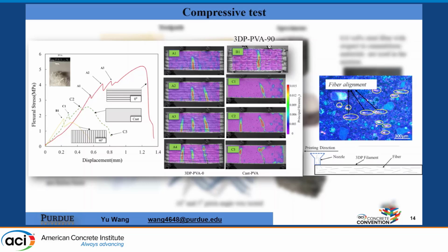This will strengthen the filament without influencing the interfacial property that much. This is a strong anisotropy, which is assumed to contribute to the microcrack development to improve the energy absorption capacity of concrete during the compressive loading condition.